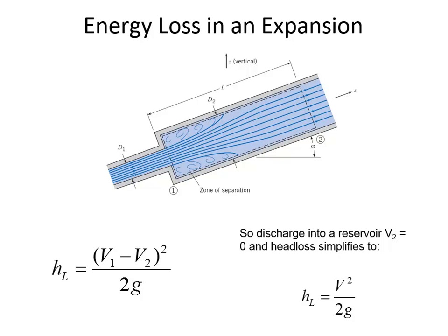Change in pressure. So it's going to be those pressure taps, the same way that you did with that experiment you designed. Remember the Hazen-Williams experiment where you were doing it between the 1 meter segments? We're going to go all around the pipe rack and measure the pressure difference at the fittings to find out how much energy is lost, and the energy loss manifests itself in a reduction of pressure.